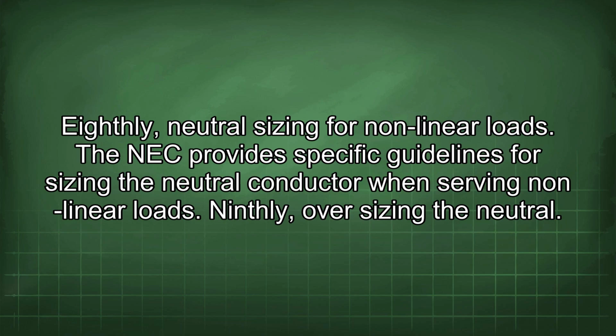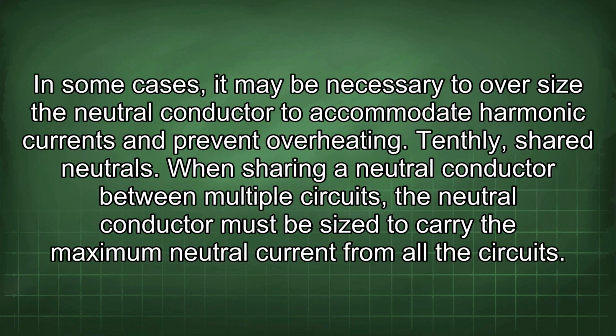Eighthly, neutral sizing for nonlinear loads. The NEC provides specific guidelines for sizing the neutral conductor when serving nonlinear loads. Ninthly, oversizing the neutral. In some cases, it may be necessary to oversize the neutral conductor to accommodate harmonic currents and prevent overheating. Tenthly, shared neutrals.